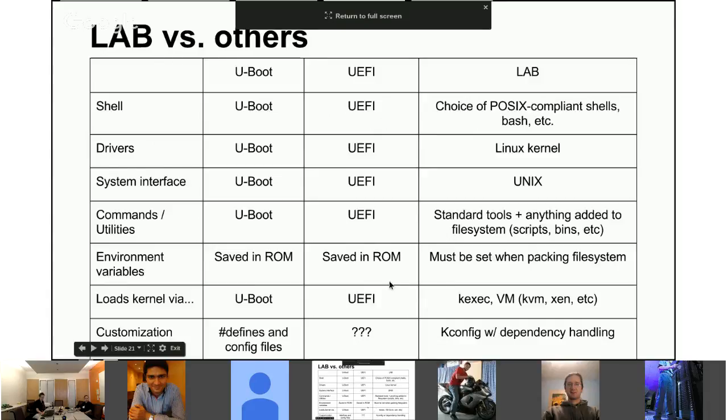et cetera, et cetera. Environment variables, we need to figure something out for the Linux-as-bootloader approach, because if you're going to run utilities and stuff, then it is nice to be able to save some state. Of course, like I said, you can bundle flash ROM with this, so you can certainly write stuff to SPI-ROM, or you can mount your file system and write your state there. But it would be nice to have something as easy as some of the U-boot variables where you just type a command and it saves a variable to SPI flash, or whatever your non-volatile storage is.